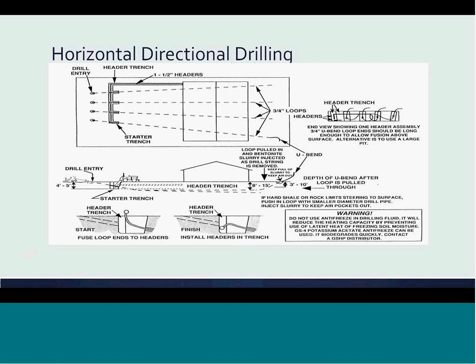The first case is more like a vertical loop system. This case actually punches through the earth in 2 places. It is recommended in most cases that these systems be fully grouted.